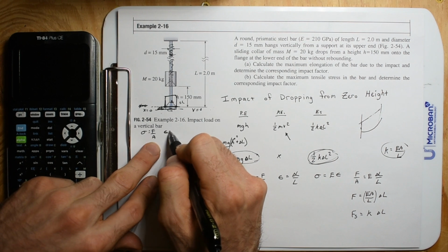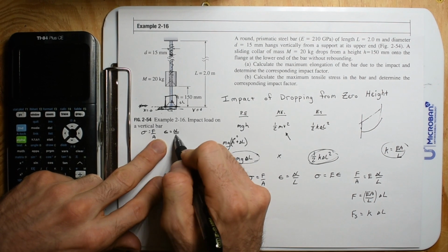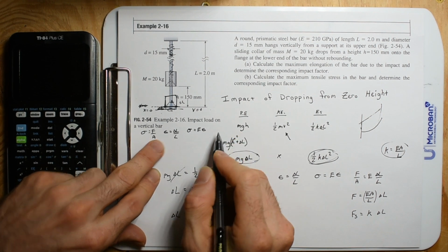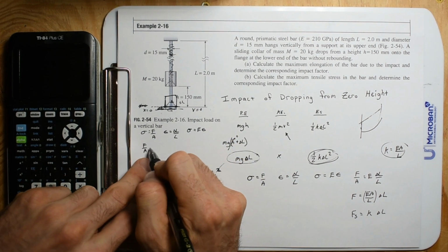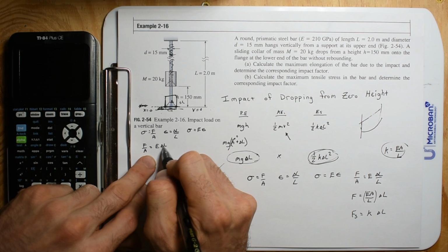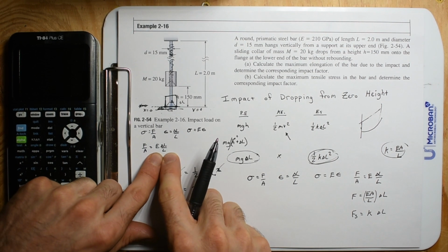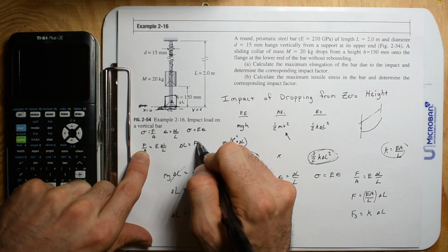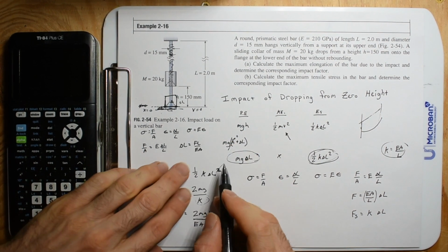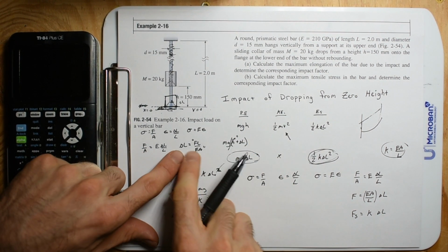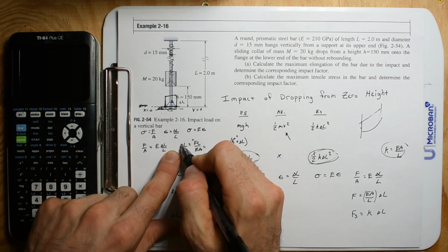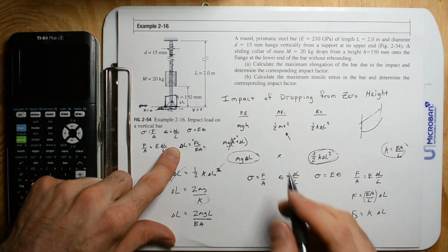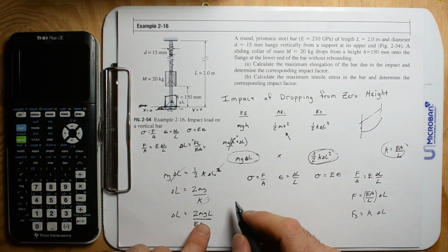Stress is force over area. Strain is change in length divided by length, and what relates them? Stress is modulus of elasticity times strain, so force over area is equal to E times change in length over length. And what are we trying to find? We want to know change in length. So change in length is just going to be FL divided by EA. And this one you should memorize by heart. Maybe it spells fleet. I don't know how you're going to memorize it. This is like, oh, okay, I'm on the right track, and we have change in length. And so let's do that.